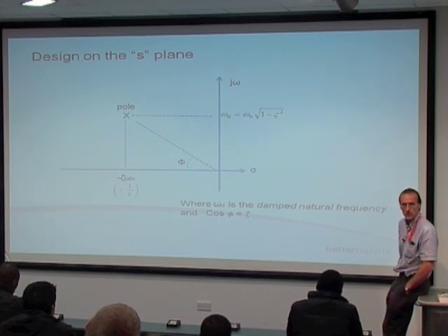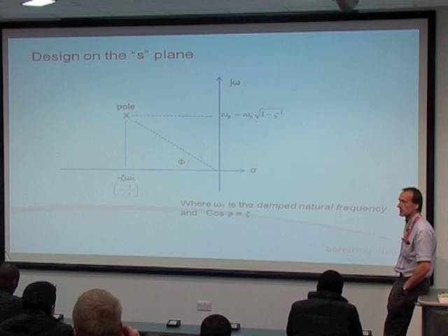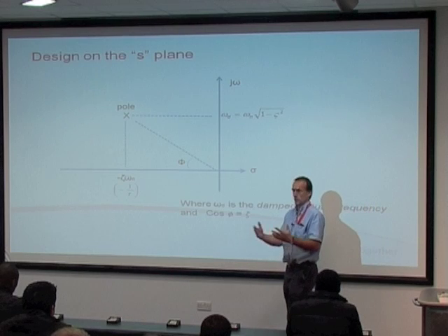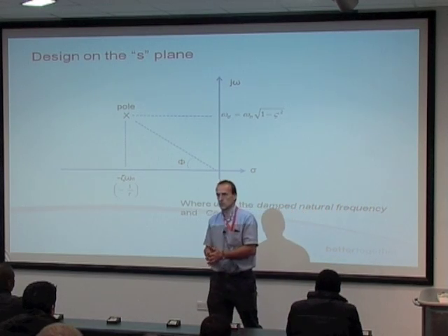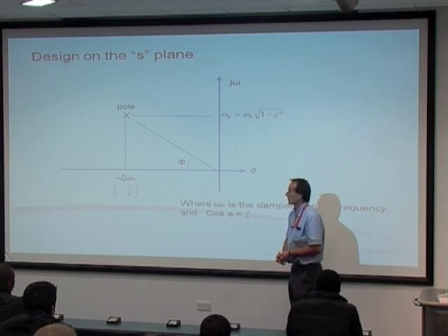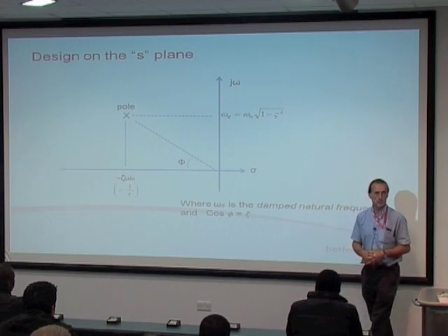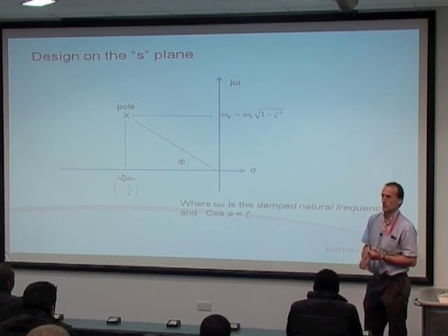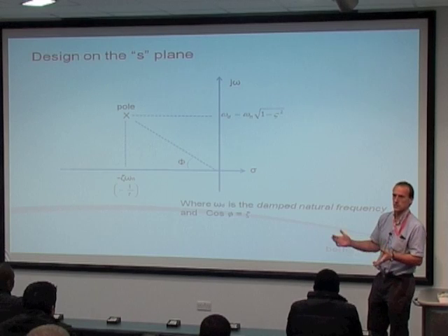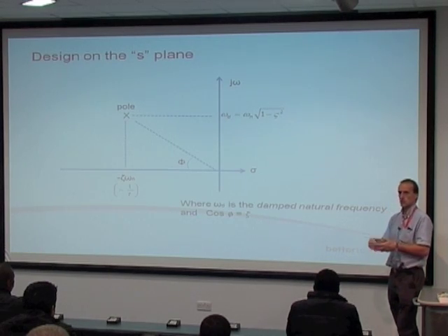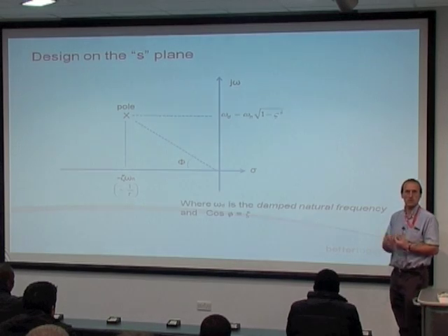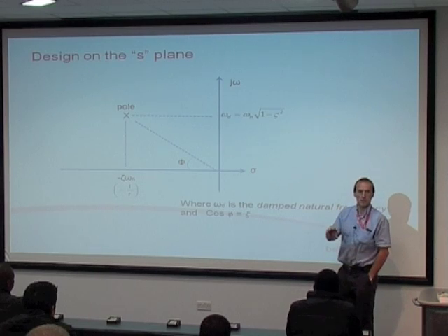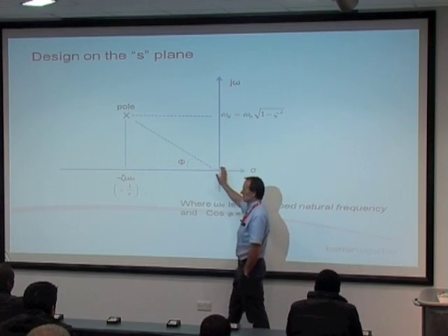We can use this S-plane to design system behavior. If you imagine that we've got a job, our job is to design system controllers, and we've got a design specification. The spec might say, right, design me a controller for this system such that the rise time is equal to or less than a particular time, maximum overshoot of something or the other. You're given this kind of information to design things. So what we can do is translate that information into space or regions on the S-plane.